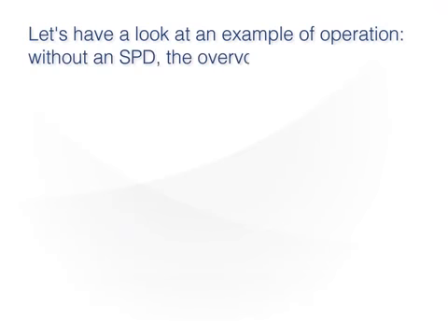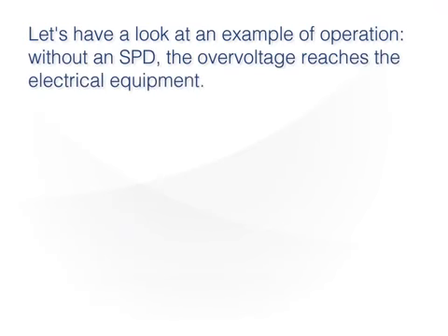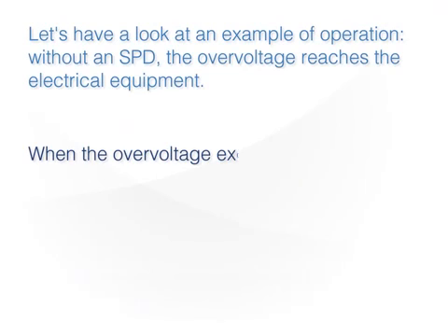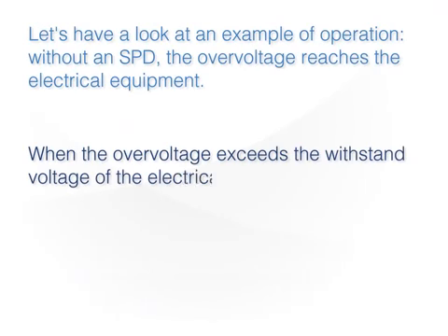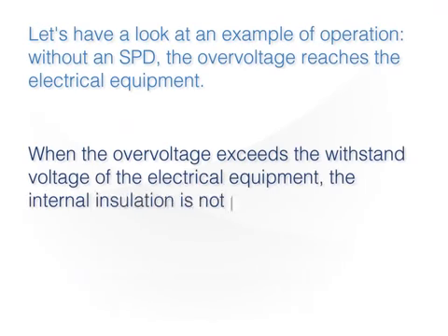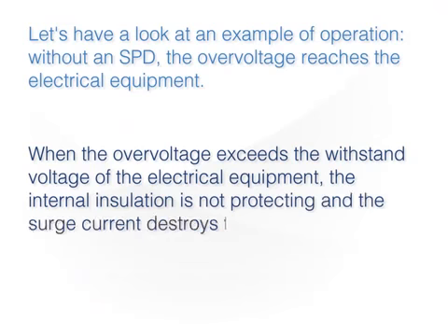Without an SPD, the overvoltage reaches the electrical equipment. When the overvoltage exceeds the withstand voltage of the electrical equipment, the internal insulation is not protecting and the surge current destroys the equipment.